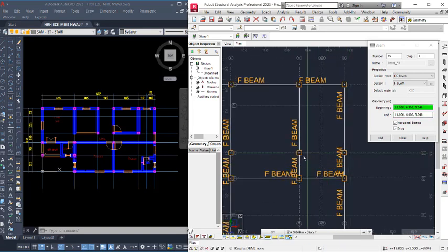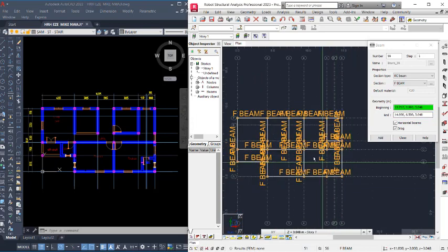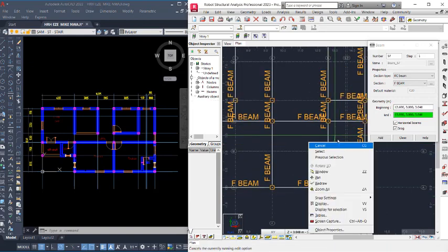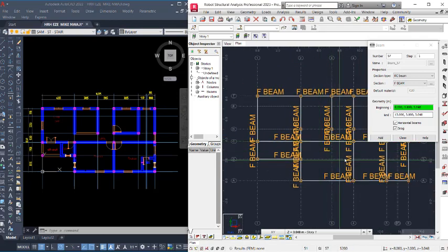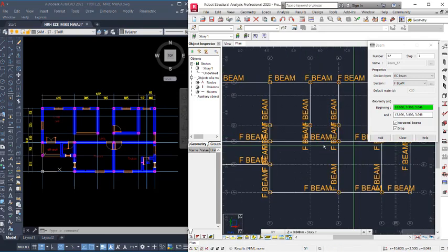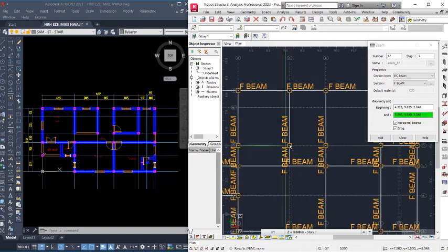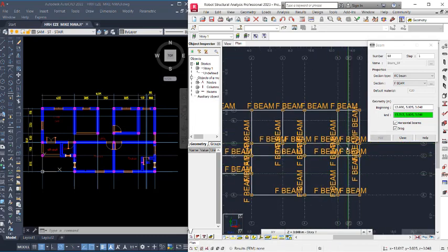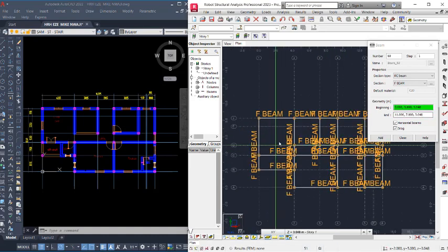We still have a beam here. This is the stair room, right? So here are all the beams. Let's have another beam in these provisions. Click. Okay, so I think this is what we actually needed. So we have another beam in these provisions, from this point to this point, just like this. Right click and cancel that. So here is our model.